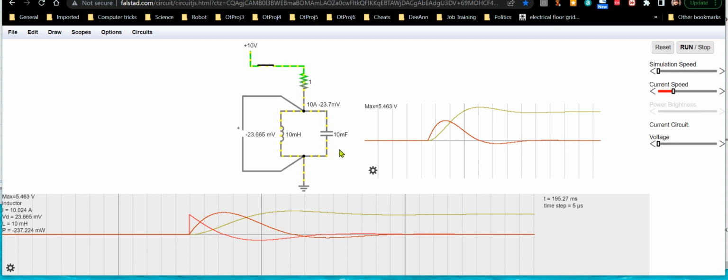But we're not going to go into that. But that is what determines the frequency of this tank circuit, because it actually oscillates at that resonant frequency. If you use it as a filter, it'll tend to block that frequency. So if you had a 15 hertz signal going through it, which is what this will end up being, it'll block that,